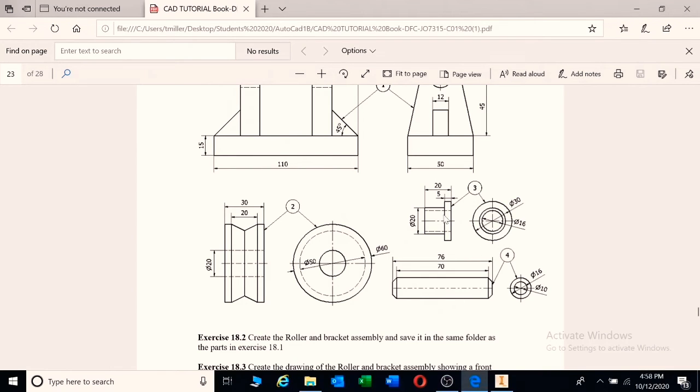Now going further, we have that shaft that fitted in there, and then we have another hole, and that hole going straight across is 16. So the 20 has been solved, so we're now left with 16. Going to the next part, and we look at these diameters, we have a chamfer there, which is a 3mm chamfer, because we have 70 and 76.